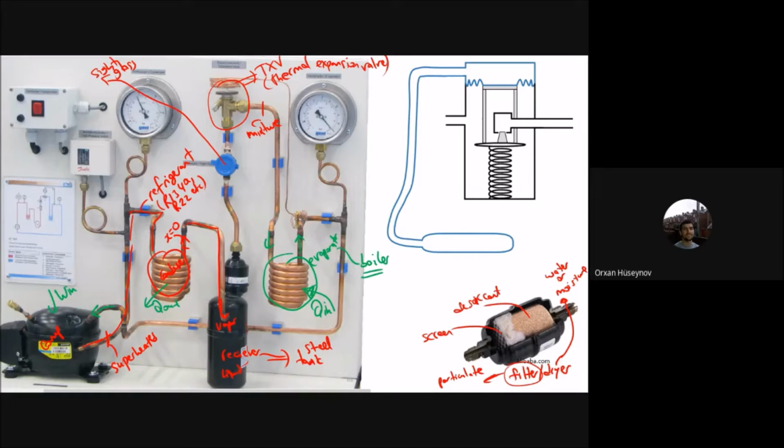And you have this pressure switch. These are additional components to maintain the safe limits for the operation of this cycle here. So you have to have the minimum amount of the permissible pressure and the maximum amount of it. You have the manometer here and you have the manometer here. So you have two manometers to measure the outlet and the inlet of the compressor. Okay, these are the main components, and the thermal expansion valve.